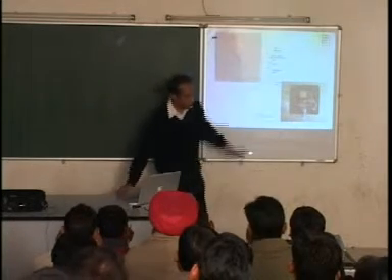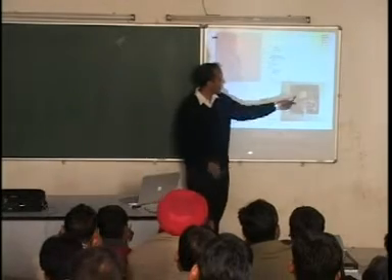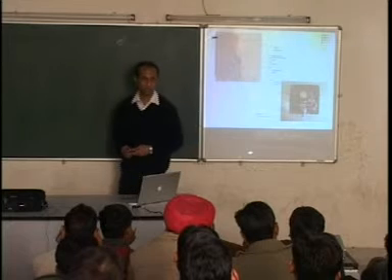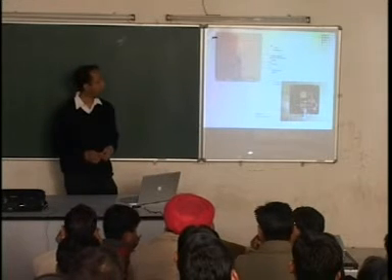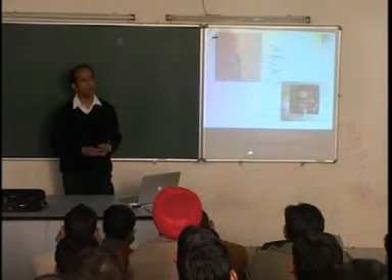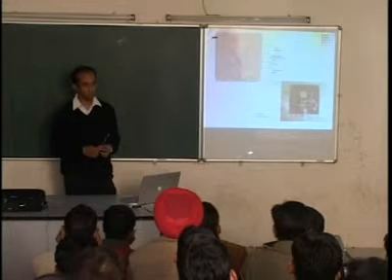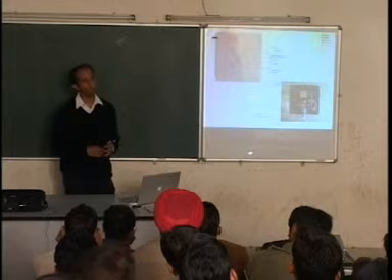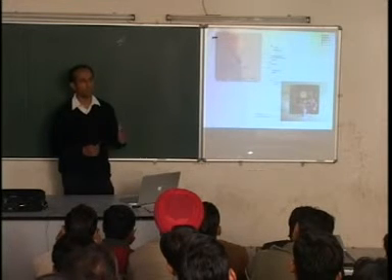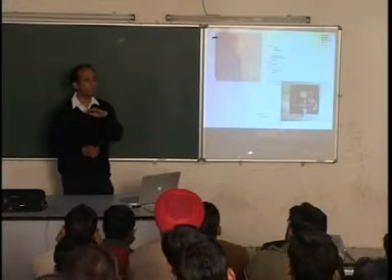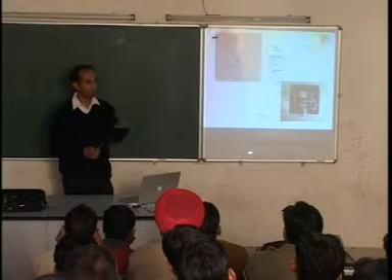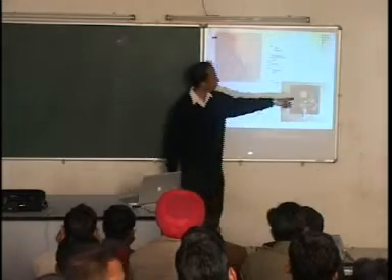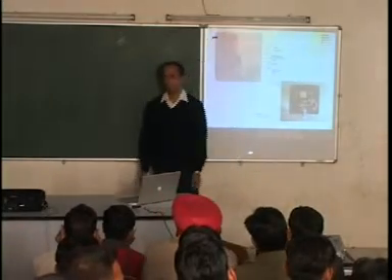So selectively you protect part of the silicon. Below this, the silicon was etched. How much was it etched? Not all of it. The thickness of that substrate was 270 microns, 0.27 millimeters, and 260 microns of it was etched out. To leave only 10 micron silicon, a membrane, silicon membrane below this patch antenna.